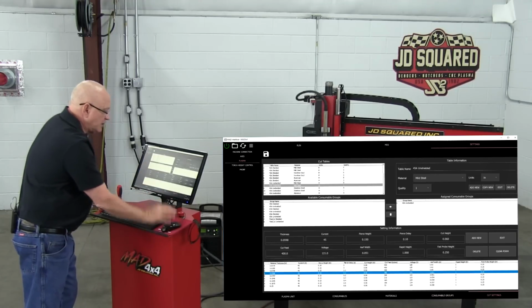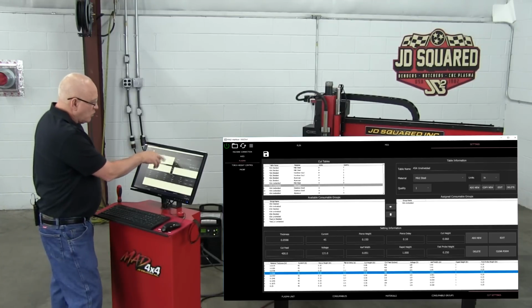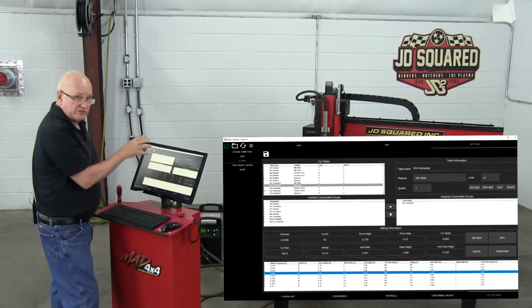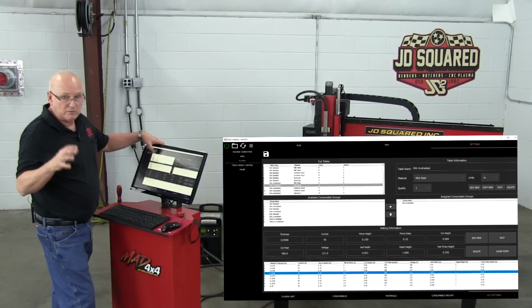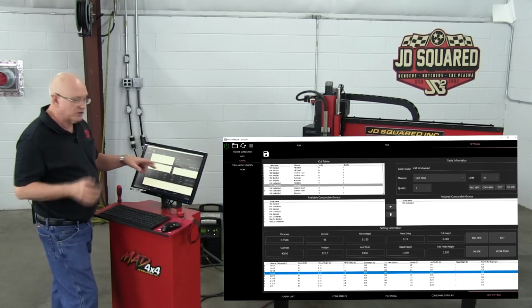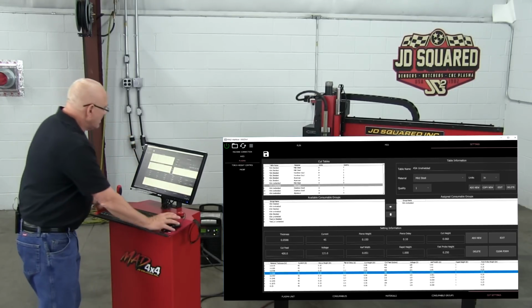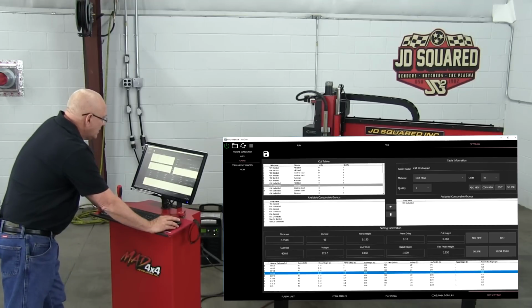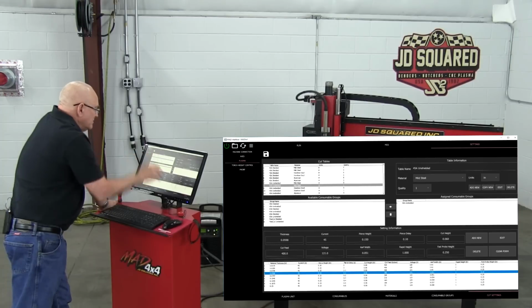If you go to the cut settings tab, here's where it gets interesting. This is where your quality, your cut units (inches, millimeters, whatever), your material, and your consumables, like 45 amp shielded, etc. It tells you your available consumable groups, what is available for that power unit. I can click on things and it will bring in those tables. For instance, I clicked on 45 amp shielded. Well, I did it on aluminum.